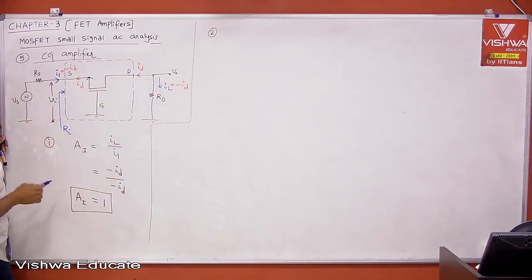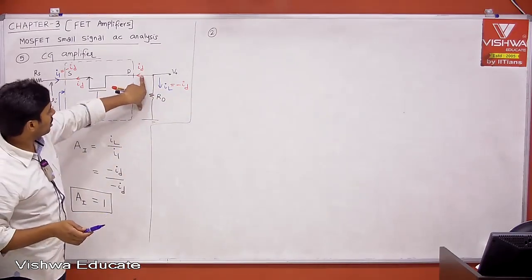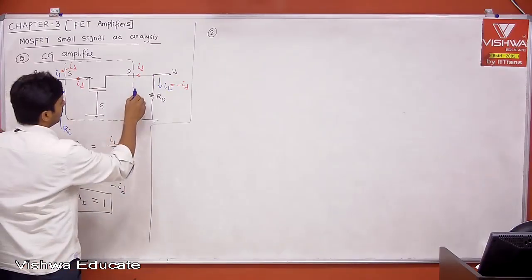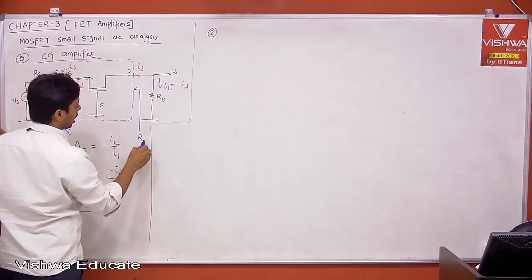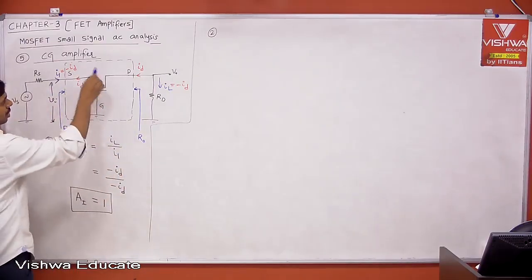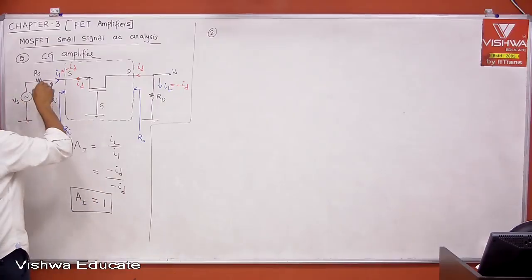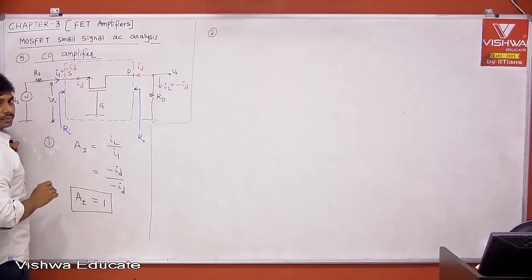Similarly, what is output impedance? Exclude the load, the impedance seen into output port when Vs is equal to 0, right? That is your output impedance. That is the definition. Actually, if you take any textbook, how they calculate Ri and R0, they replace the MOSFET with the equivalent circuit that I gave, then apply the input voltage, get the input current, take the ratio, and that is your Ri, right?